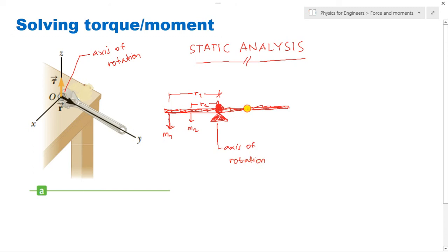And then here, mass 3 is suspended. And at the last, mass 4. For mass 3, we have R3, its moment arm. Then for mass 4, we have R4. Okay. Class, if there is no rotation, assuming nothing moves, you can do summation of forces, but the best way to solve this is summation of moment. But the summation of forces still applies.